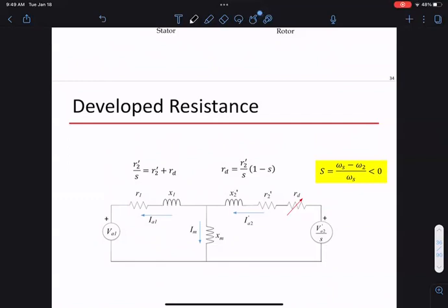Then as we develop more, type 2 and type 3, you start seeing that the fact it is in a wind turbine will start to matter. Currently, it does not matter. It's the gearbox deciding the frequency, the slip, and then we go from there. Okay.